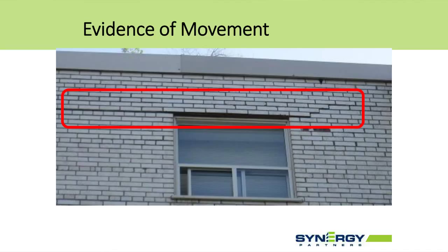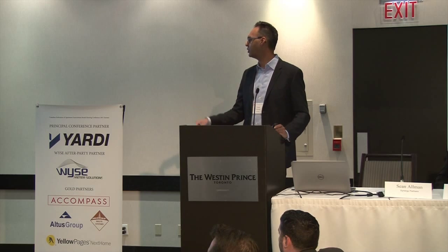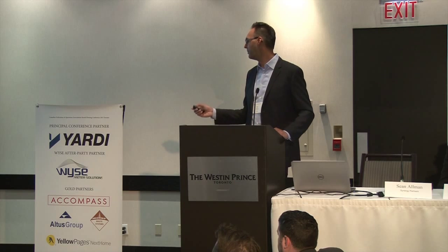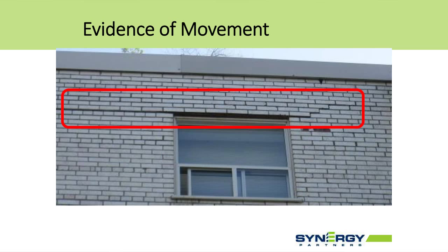So this is another example of an elevation on the same building, and it's just a different wall area, but similar. Water is obviously getting into these shelf angles and causing them to corrode. So this is taken with a zoom lens, and from grade, this actually was more apparent than the other shot that I just showed. But keep an eye out for this sort of vertical differential movement. You can see that there's a gap forming just above where the shelf angle is. So that's an indication that we're getting some rust jacking going on at this building.